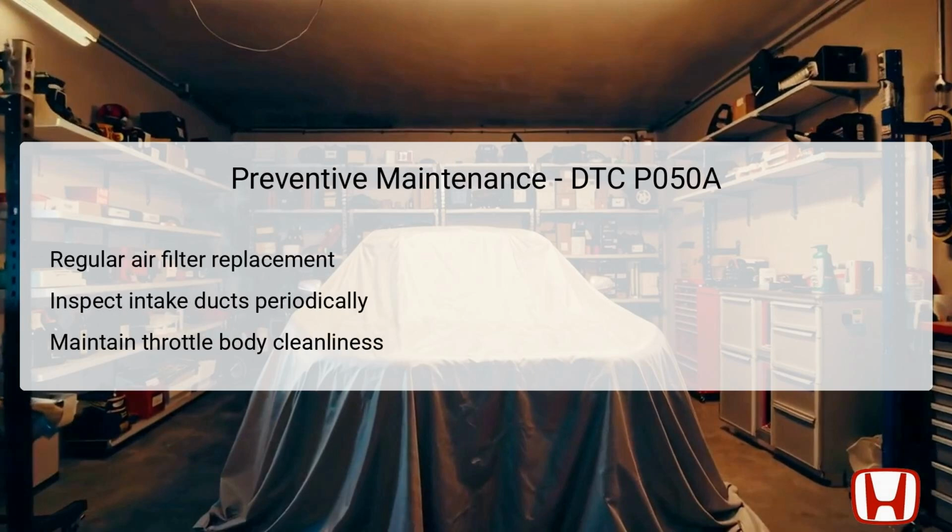Preventive maintenance plays a vital role in avoiding issues related to DTC P050A in the future. Regularly replacing the air filter is crucial to ensure optimal airflow to the engine. A clean filter helps maintain engine performance and efficiency. Periodically inspecting the intake ducts for any signs of wear or blockages can also preempt airflow problems before they exacerbate into more significant issues.